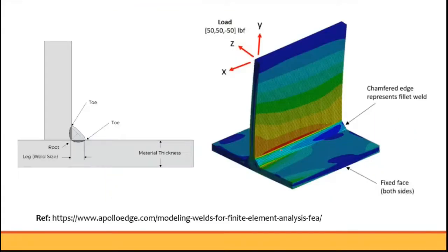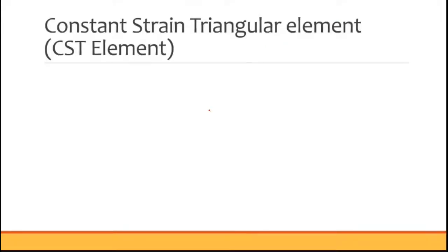So what are the other problems? Look here, you have a weld joint. Let me consider you have a T joint, something like that, and you are welding it. I'm going to concentrate on this welding part. What is the stress developed on this welding part? If I draw it, it will be a small triangle like this. But what is the thickness? The thickness of the triangle is very, very large. So you can solve this by using plane strain condition. So that is another part. This is the overall difference.